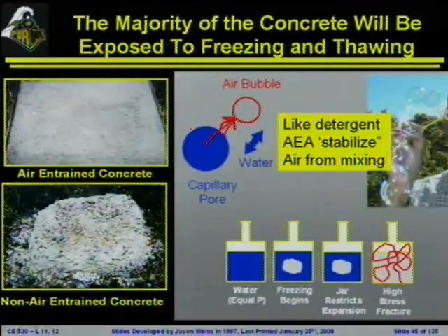But when you say completely sealed, you remember that our paste isn't a solid. It's a porous material. So the whole thing is being percolated by our capillary and gel pores. So the idea that there's a solid that's completely sealing it off is a little bit different. What you really have is, I don't know, like one of the finer micro Swiss cheeses with a big hole drilled in the middle of it. So you've got a porous system with some bigger holes in it. So the pores are all relatively connected.